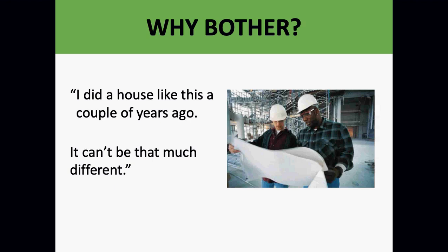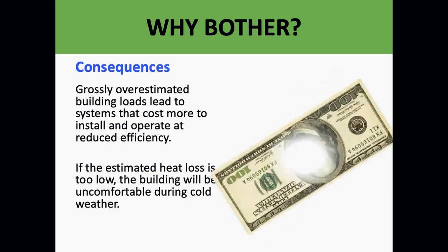Also doesn't work: this contractor's more into the size. If it fits into the space allowed, it's properly sized. In other words, if the furnace fits, it's properly sized. Contractors who are doing entire subdivisions may buy a truckload of a single-sized piece of equipment but not realize the way the house faces, if it's on a hill or not, is going to be a big difference for air conditioning and heating costs. So again, these are all excuses that we've all heard on why people did not do load sizing.